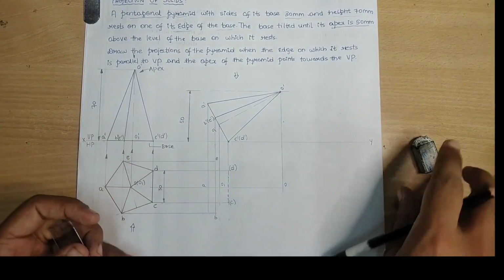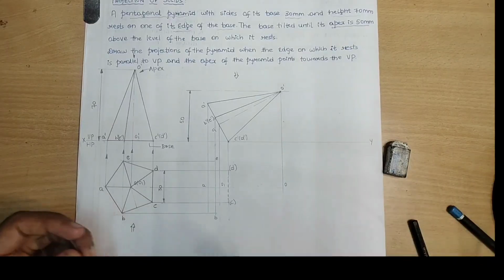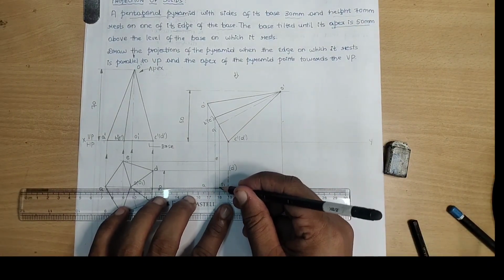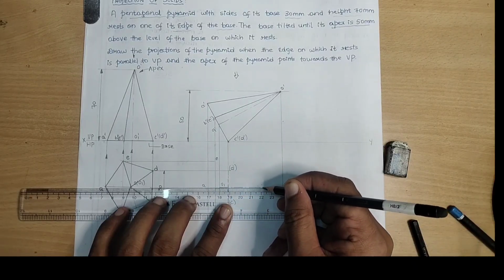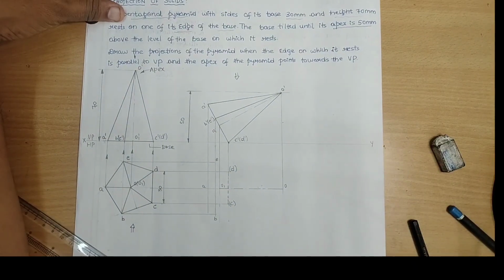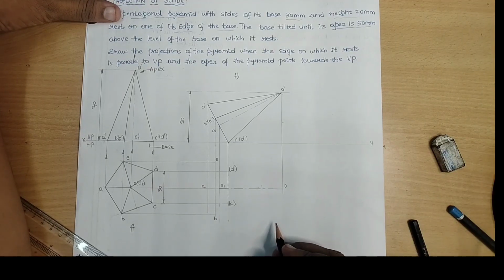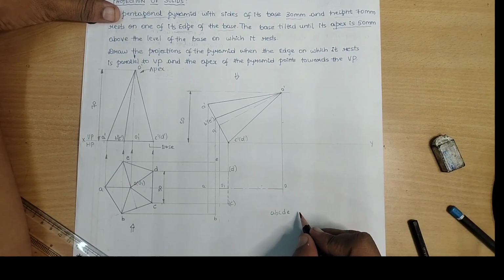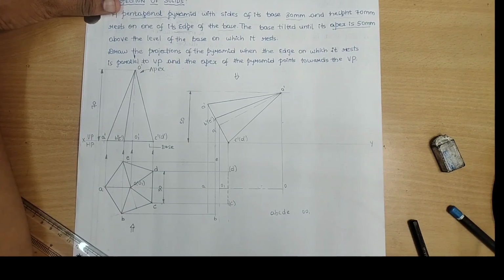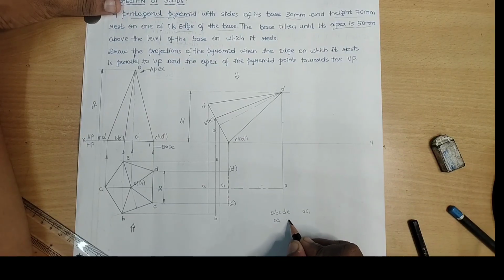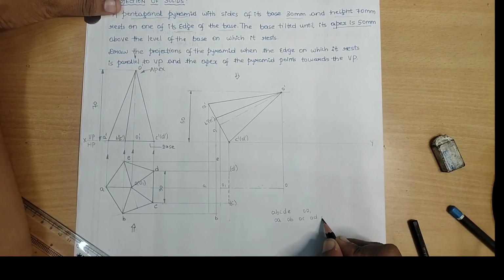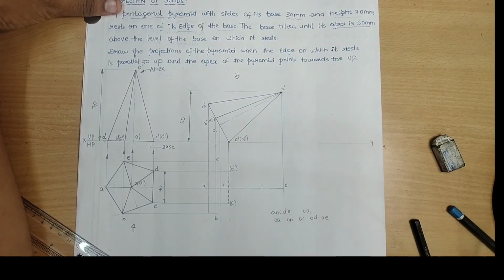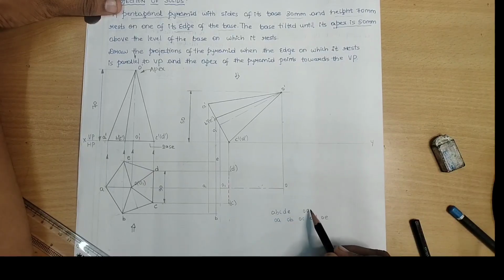Thick dash lines. And what is the condition of O to O1? O to O1 is always the axis. Let us draw it as an axis line: big line, small, and big and small. Towards the side of the paper, we can write what all has to be drawn here. The first is A, B, C, D, E. The base geometry has to be constructed. We are supposed to construct a line from O to O1. We are supposed to draw a line from O to A, O to B, O to C, O to D, O to E. I mean to say that for the apparent shape and the sixth position here, these many lines have to be drawn. Okay, first let me construct O to O1.